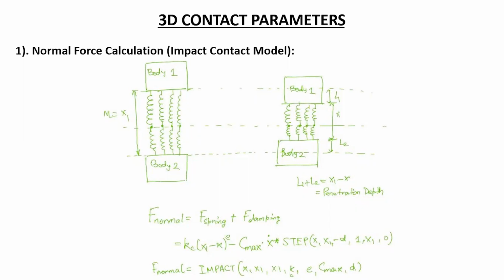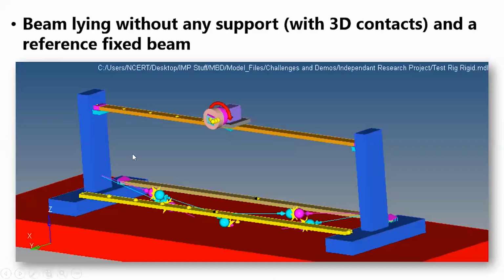So basically, for normal force, in the previous cases I was calculating the joint reaction forces. Now in this particular case, I don't have any joints. I need to calculate the reaction forces between this beam and this stand. Now, what does reaction force constitute? It constitutes a frictional force between this surface and this surface, and a normal force between these two surfaces, between these two bodies, right?